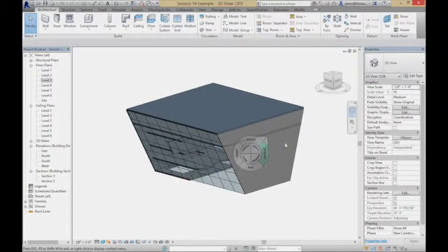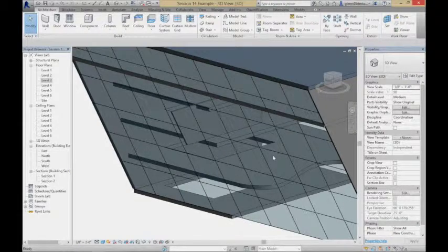So what do I want to tell you about this relative to your workflow? It's the whole notion that if you're going to go ahead and use sloping walls, that's super. It's going to be a little bit more work in terms of trimming up the walls. That's okay. We can do that ultimately. But if you are going to do that, go ahead and save that for kind of one of your last steps in the process. If you're still working with a form and you might reslope it, you might move that wall, go ahead and put walls in, but have them stop short of the sloping wall, with the idea that you're going to clean it up later, because cleaning it up as a manual process is just kind of messy. It's not an easy thing to do.